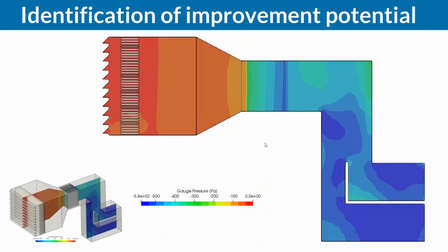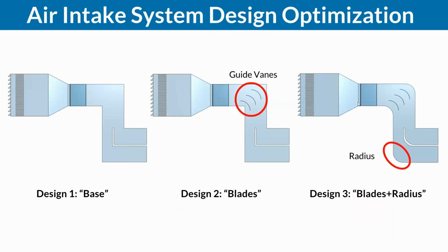And the pressure field helps me to see where I'm losing pressure, right? And obviously I'm losing here in the beginning through the filter parts. I'm losing then via the cross-section change here. I'm losing a lot via the silencers. And the interesting part that I want to take care of now is the losses that I'm seeing here, right? At the 90-degree change of direction.